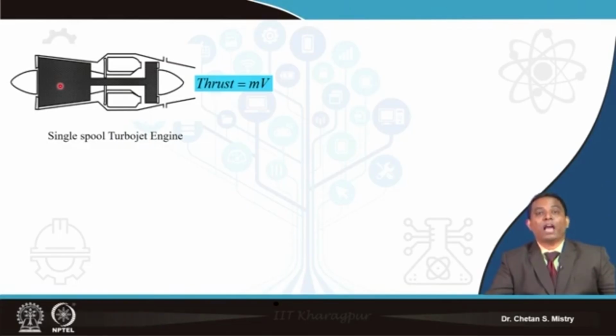Now when I say I am looking for a higher pressure ratio, that means the number of stages required for this axial flow compressor will be larger. That will increase the length of my engine, and that is a constraint for my aero application. Second option: you may be aware of the fundamental equation called Euler's equation, which we will discuss at a later stage. The power generating or power absorbing capacity of turbomachinery is a function of my rotational speed.